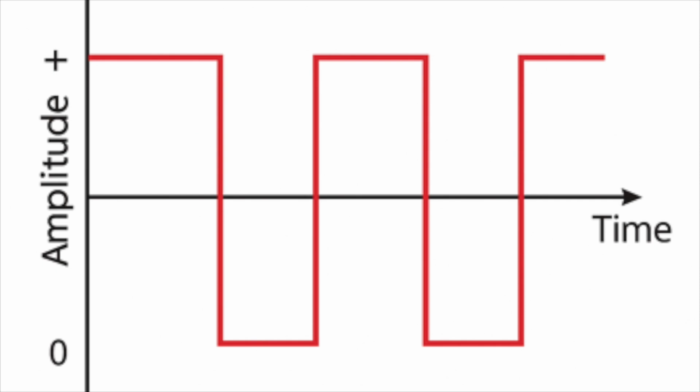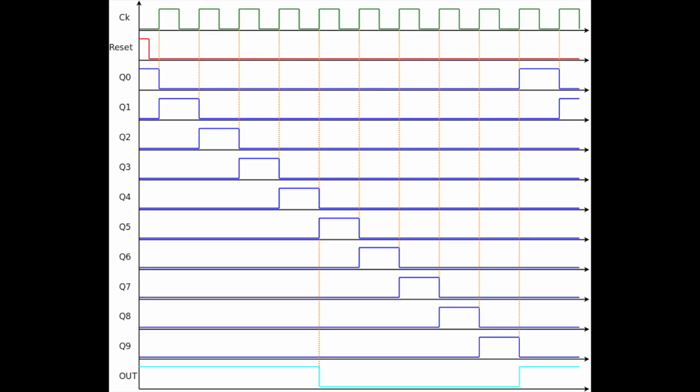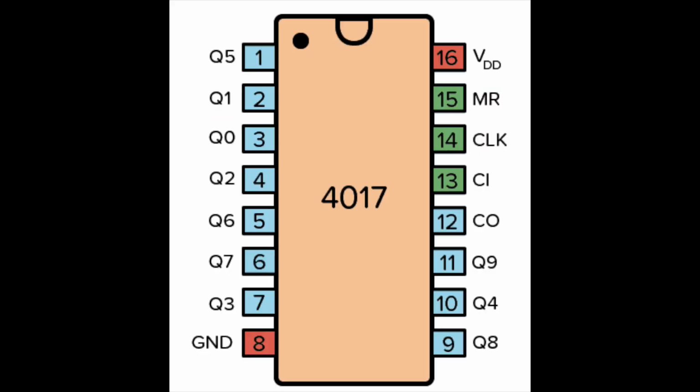full oscillation. The decade counter uses the 4017 IC to harness the NAND gate oscillator's oscillation and use it for 10 LEDs, which receive high and low in order, relying on the oscillation to receive a signal. This IC also has a divide by 10 pin, which takes the oscillation and slows it down to 1/10 of the received signal. In the counting circuit, this chip is only used for its divide by 10 pin.